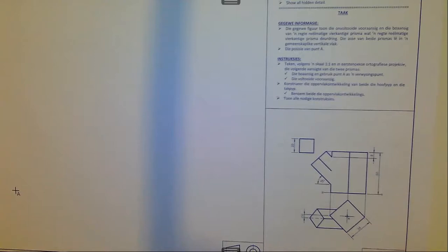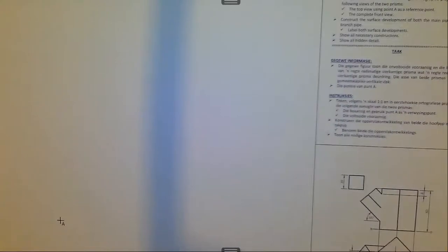Right, one key characteristic that we find with regards to offset combination is that there has to be hidden detail, because you are not going to see the other details from the other side. When it is an in-line combination, you would find that the details fall basically in line. The detail which is in front is basically the same as the detail which is at the back, okay? But the moment you are able to see that there are certain details which you are not able to see, which are at the back, that is a typical offset combination, okay?